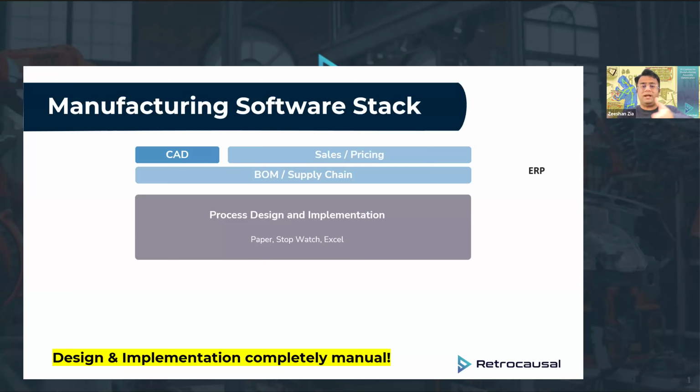They'll figure out how to break that work content down into work instructions amongst the workers, where they'll have to figure out the workstations themselves. Where does the test equipment go? Where do the bins go? Where do the fixtures go? Then they'll figure out the material handling piece, right? How do we keep these stations supplied with raw materials, with parts from the local warehouse? And then finally, they train the operators and make sure that the operators are actually following through with the work instructions.